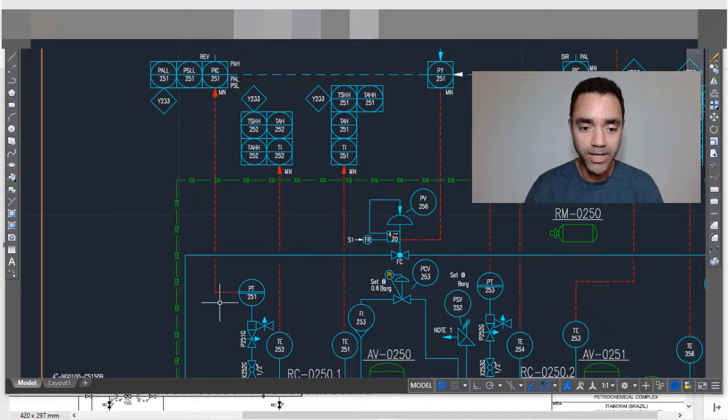So if the pressure decreases and I need to return my pressure to the desired condition, the signal that I will send to this control valve is for opening. I am reducing the pressure at the suction, and I will increase the signal so this control valve opens. So I have reverse conditions for my process, and because of that it is reverse.